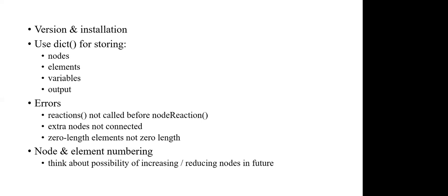For example, all your nodes are 100 apart, but two nodes are 0.1 apart. Or for some reason, you are dividing the elements into 10 divisions, and Python does some weird divisions. Sometimes you get 99.09999 and there is another node at 100. If you have two nodes like that, then that kind of error also pops out.